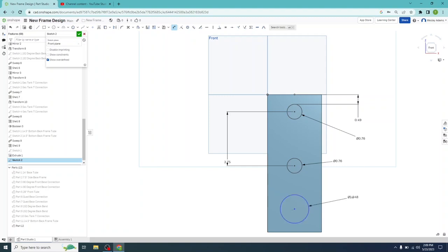And let's set the diameter of this one at 0.76, hit enter, and let's set the distance between the outer part of the diameter of that circle we selected, and let's also select this line here, and let's go out here, and let's make that 0.25, so 1/4 inch. That'll move that one down. And then let's select that center point, this center point. Let's draw that out, and that should be 5.5 inches. That's where we want it, so we'll just leave it there.